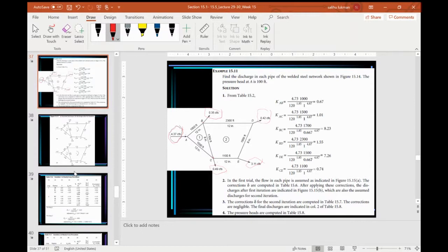select the pipe size. And when we select the pipe size, we now compute K for each pipe. We compute K, which is the resistance coefficient, using either the Hazen-Williams formula or the Darcy-Weisbach formula. So we compute K for each pipe and solve for flows in each pipe through the iterative procedure, which we did in the previous example. Once we do that, we should confirm that each pipe carries the quantities required for that segment and recheck the velocities in each pipe.